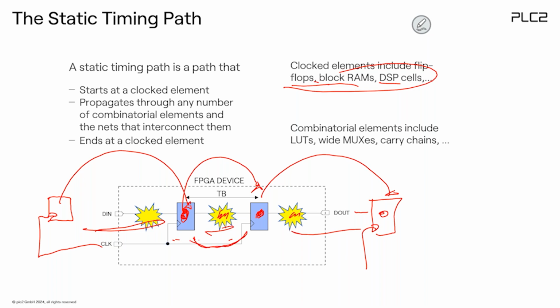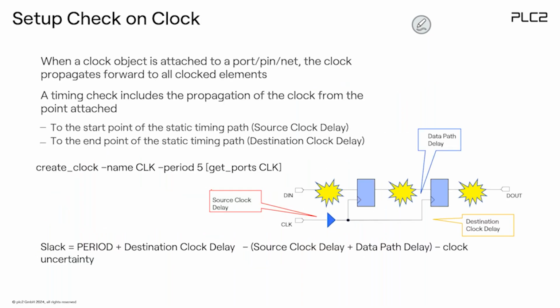So in my example here, the path from here to here has a maximum delay of the type TB, whatever this is. So that's actually the point. That's really what happens during implementation. In Vivado, we define a clock here, and then maybe we also define some timing from here to here. So this is a starting point. This is my FPGA. Once we define this, it's the only information which is needed by Vivado: the clock and the data in.